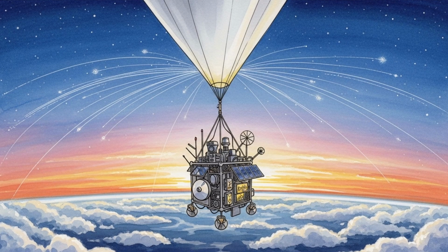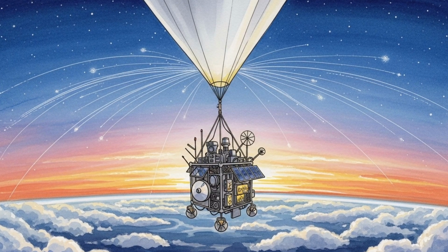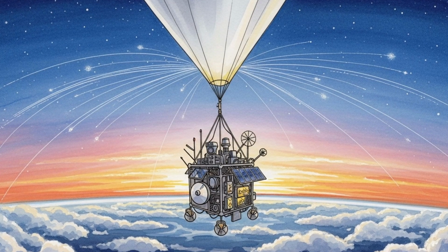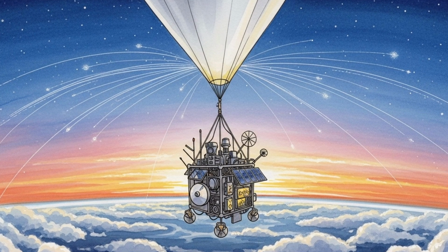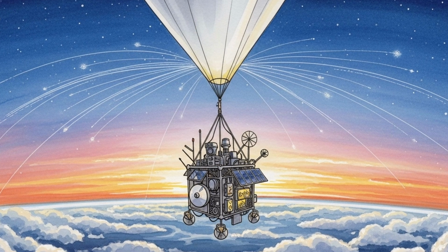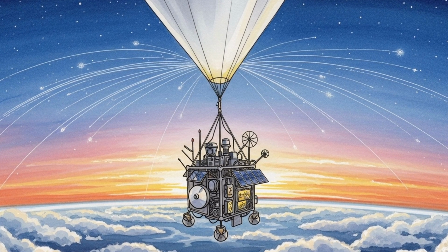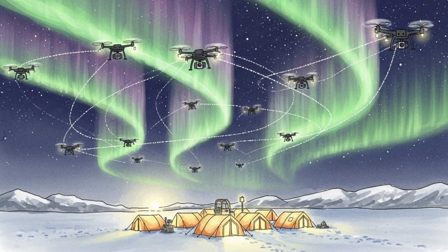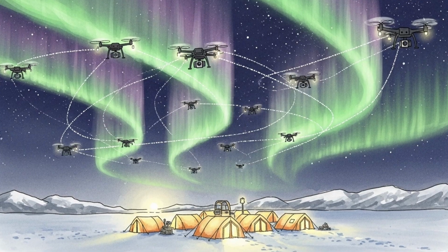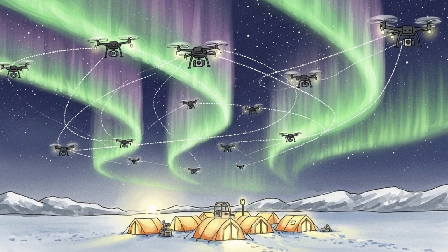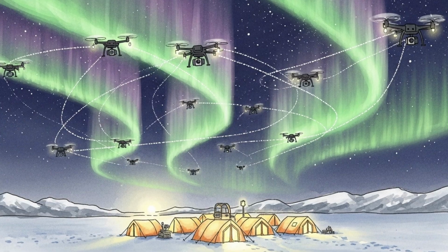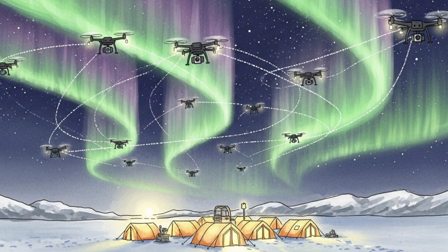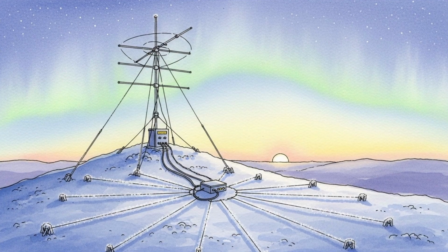In summary, aviation faces higher radiation levels on polar routes, periods of degraded high-frequency communication, and temporary navigation uncertainty. Standard mitigations are rerouting, altitude changes, and alternate links. Astronauts face higher radiation exposure and operate with shelter and activity limits during events. Dosimetry, conservative timelines, and clear go or no-go rules keep exposure within program limits. The combined effect of these measures is controlled risk and predictable performance during strong solar storms.